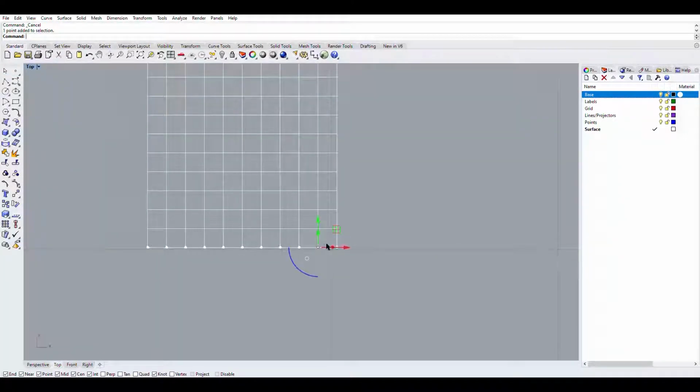We can go through and kind of clean this up, so I'm just going to select all my points that I don't really need right now. They were my reference point. They're showing the filter or no? Yeah. Oh, select points? Yeah, if you go down to filter, down here, you can actually just right click on points. And then now when you're in your workspace, the only thing that you're going to select is points. I don't know if it's going to work because you already, oh yeah, there we go. So you'll notice that even though we kind of dragged over those lines, it didn't actually get rid of them. It was only selecting those points. Yeah, and actually right click is very important, because if you left click, you'll have to select all of these, but right click will hotkey any of these that you're going to want to actually select.